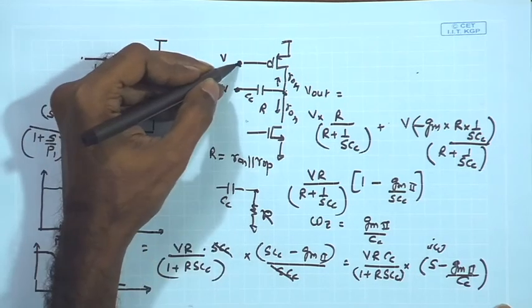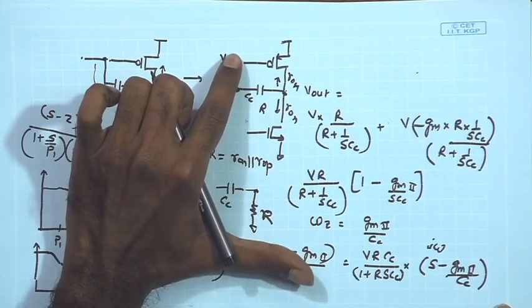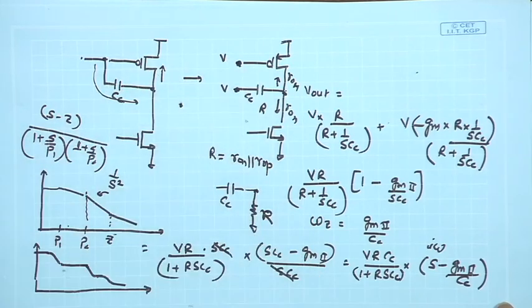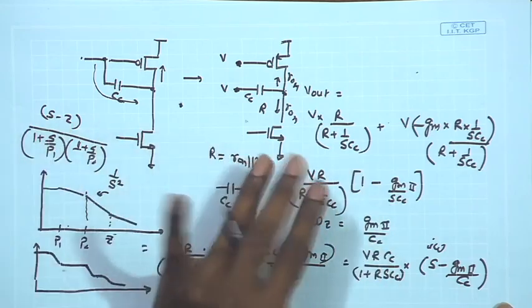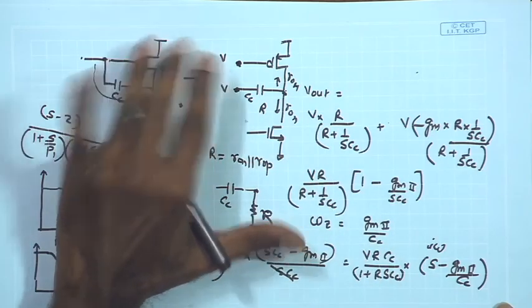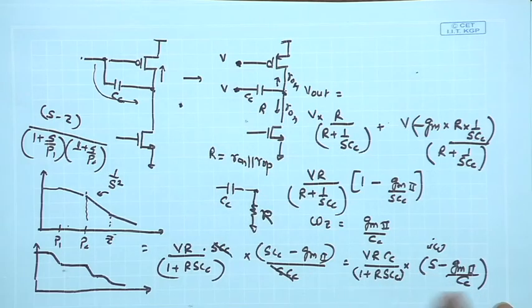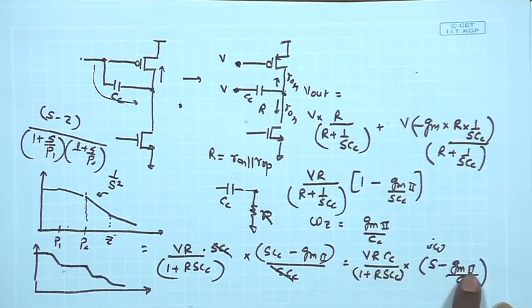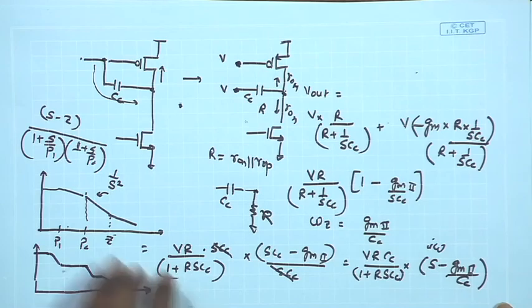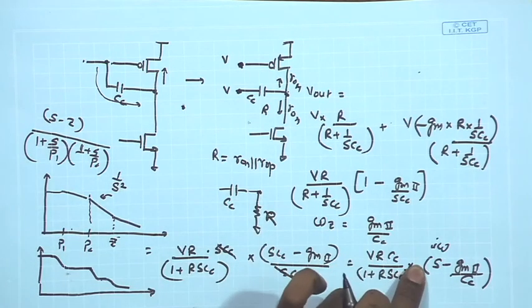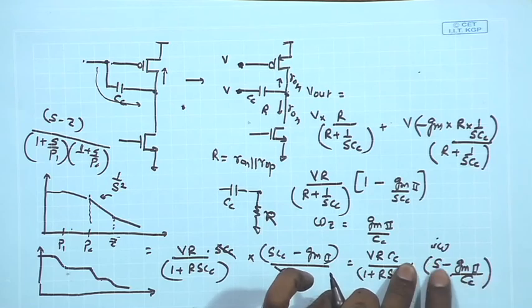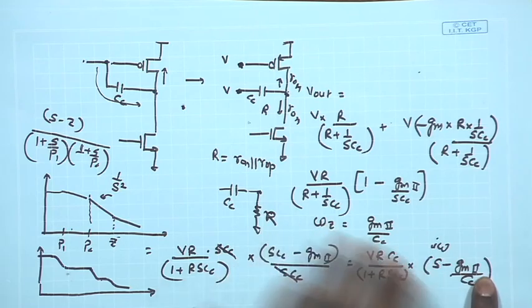So, if I look at the signal from here, you have an overall negative sign coming from the previous stage, and multiplied by that it will give you an expression which is minus gm pi cc minus gm. So, that is already giving you a negative sign. So, this will basically be gm upon cc minus s. So, it will get inverted.